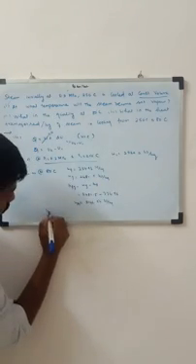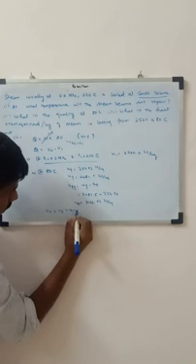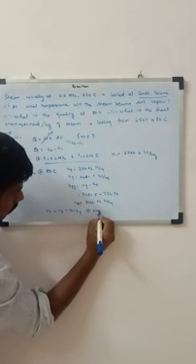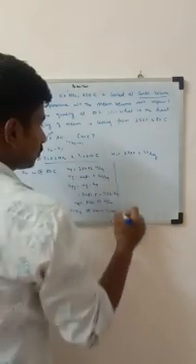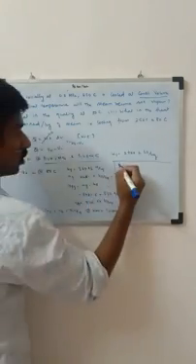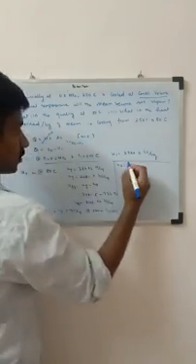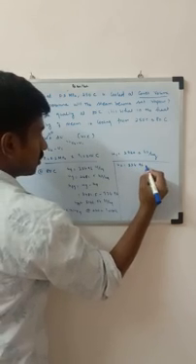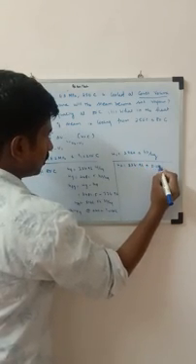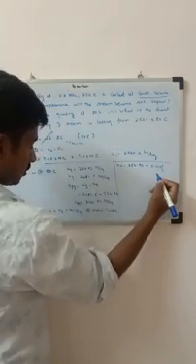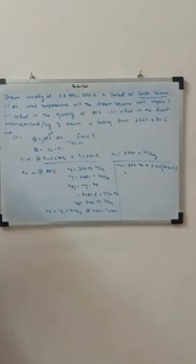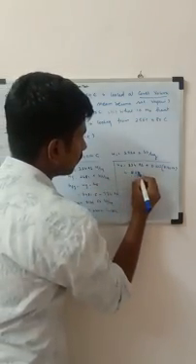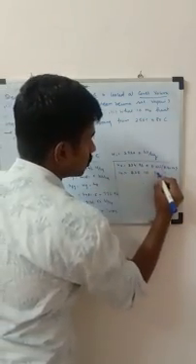And this is my UFG. So therefore U2 is nothing but UF plus X into UFG at state 80 degrees. So I'm going to put all these values. Therefore my U2 is equal to, what is the value of UF? UF is equal to 334.96 plus X value is 0.233, UFG value is 2146.54, which will give me a value of U2 is equal to 835.10. So this is my U2 in kilojoules per kg.